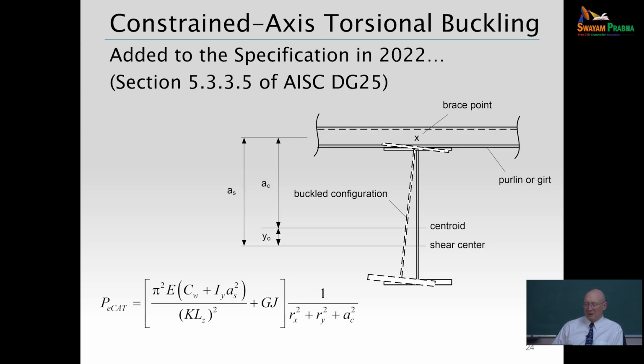However, potentially we could have flange diagonals that frame from the girt or purlin and then provide bracing to the other flange. But those are expensive. Again, one process that metal building manufacturers often do, they call it essentially a bracing diagonal reduction stage.